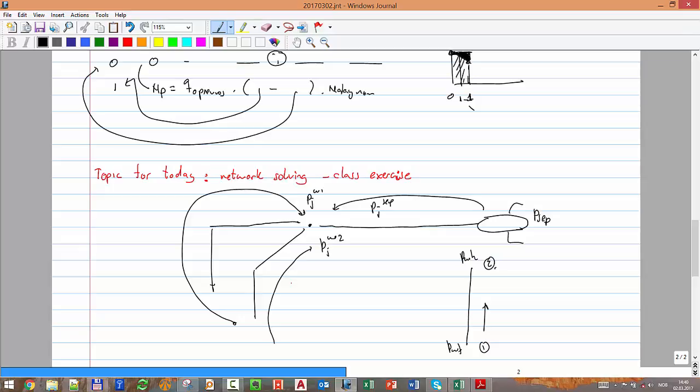Now is the crucial step. I have to move from this point, from the wellhead, to the junction, right? But there I have one flow line, and I have actually 2 more wells, or 3 more wells in the case of template L, that are very close to it. So I assume that all the wells have the same wellhead pressure, because they are so close to each other.